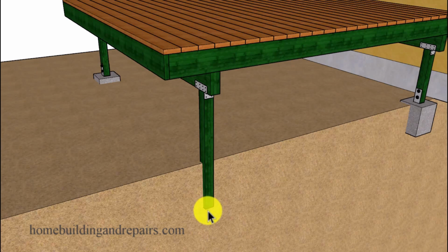A lot of times you're going to have a small footing on something like this, or a concrete block or a couple of bricks underneath the post that's sinking into the soil. Now, I do have a video on how to fix some of this stuff at our website, because for this one here, you could simply pull the nails out of this and then put a block underneath the supporting beam so that you wouldn't have to remove the post if it wasn't damaged. And keep in mind that some of these repairs will need to be repaired again in the future if you're dealing with soil conditions that will not allow the footings to structurally support the deck.